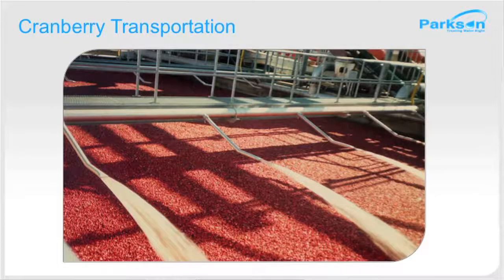Here we are seeing a cranberry processing facility, basically. And here, after harvesting the cranberries, they bring them into this pond, and they transport them by spraying water through these nozzles into this pond. And after the cranberries are transported, how do they separate them? They separate them by using Rotoshears, and they reclaim the water and pump it back to these nozzles. By doing this, they are saving a lot of money by not bringing new water in. This is one way of using it.